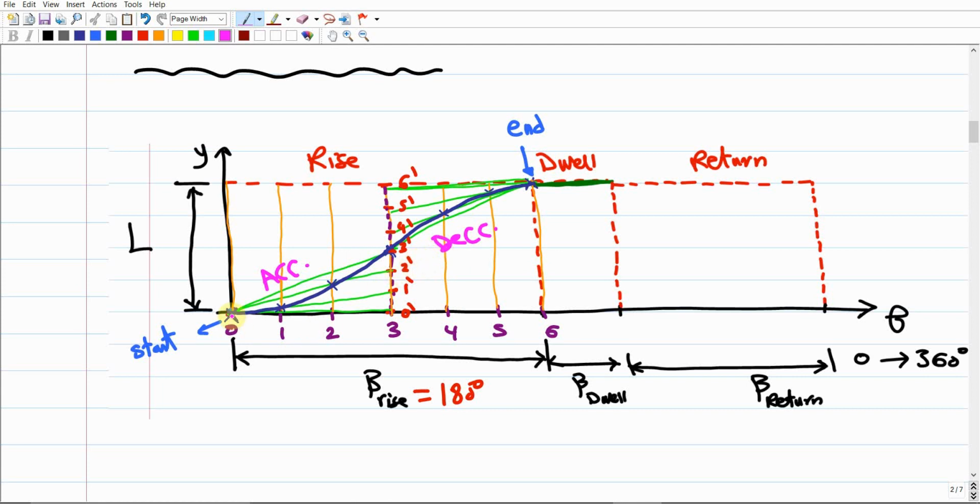And this makes sense. We are going to increase the velocity to be maximum in the middle, as we discussed in the previous meeting. Then it's going to decrease again until the dwell. Then it's going to return to 0 velocity and be stationary. Then we're going to start the return motion again, right? So I'm going to repeat what we did for the rise motion with the return motion, typically the same. Make sense? So in general, in the return motion, we basically start from that point.